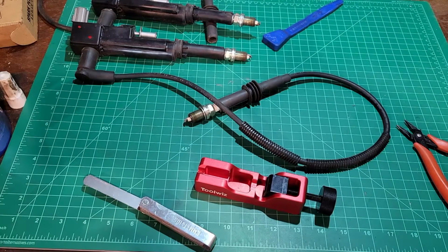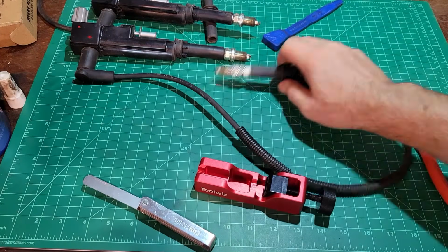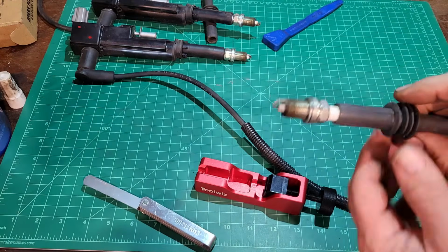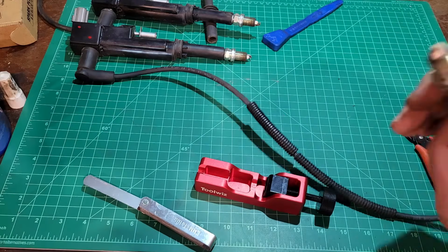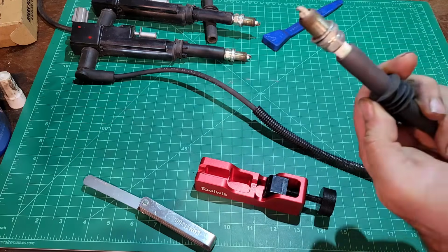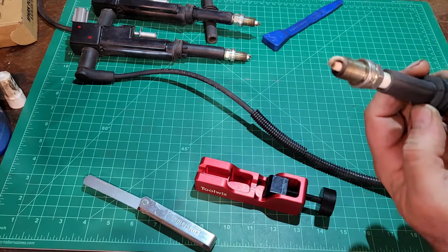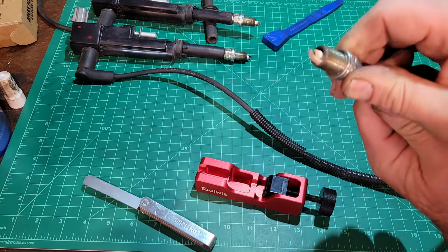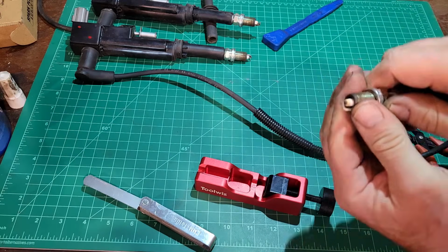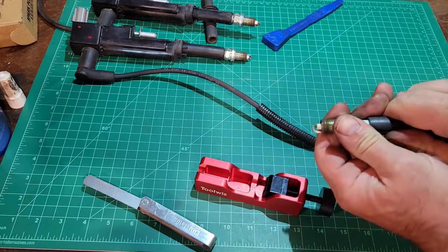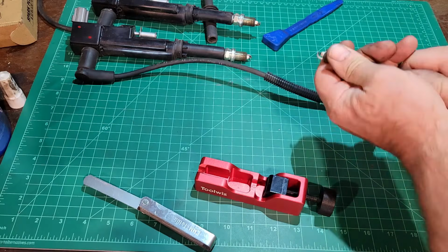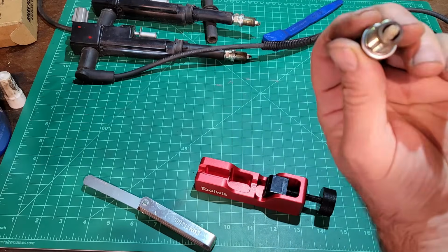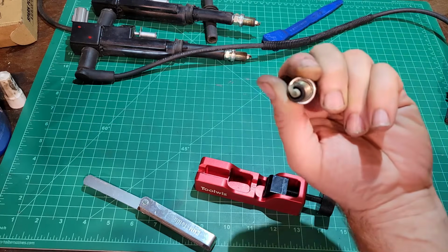All right, just looking at the differences in spark plug gaps, the main thing is I could tell these were replaced. So somebody wasn't BSing her. The one wire being a little bit out of spec, that's not going to affect much. Now, they were either pre-gapped for somewhere around 35 thousandths or somebody dropped them, whatever the case may be, but they're not that old. I don't generally like re-gapping spark plugs, but just to get a baseline, you can even see the crush washer's still intact.